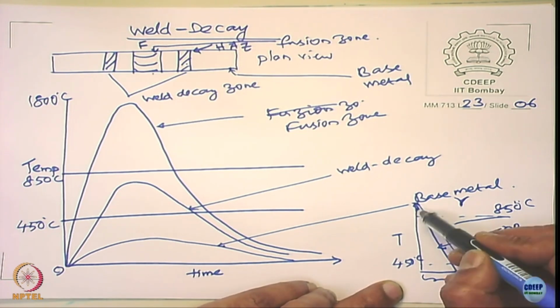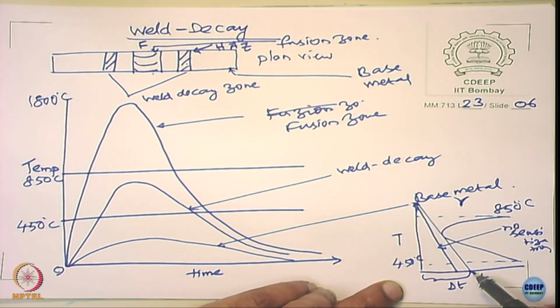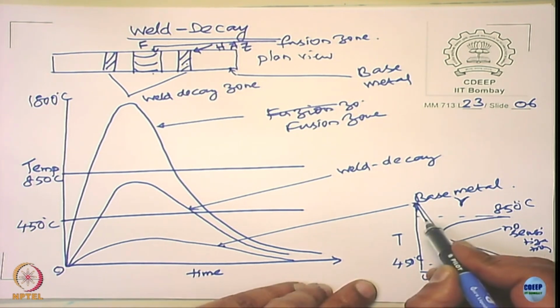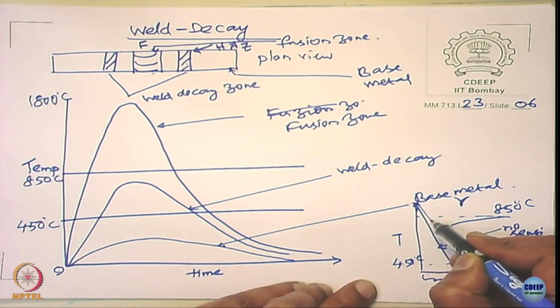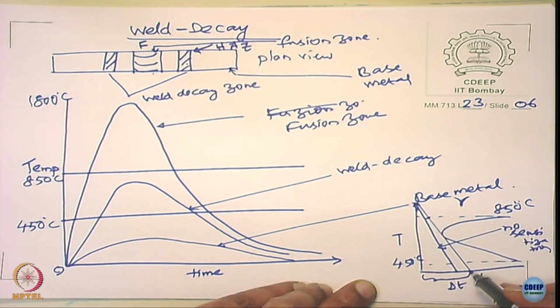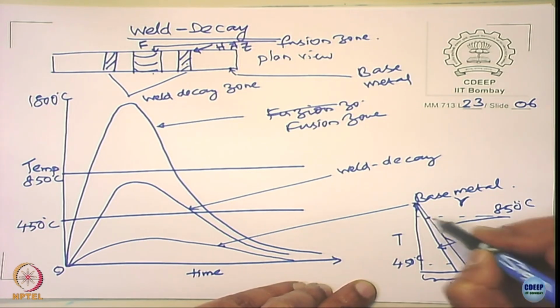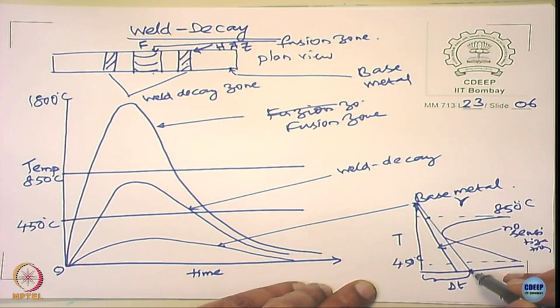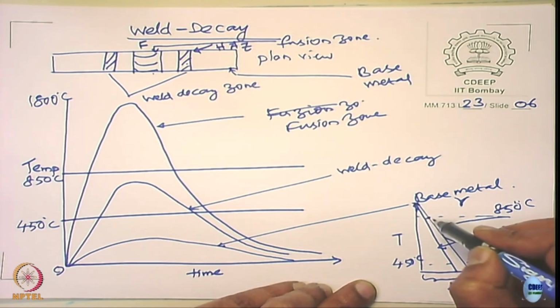So when you take it to this temperature, if you cool it faster than this, that means less time, no problem. Slower than that, you get into sensitization. That means the time that can be held in this temperature region, or actually speaking you should go from here. If you really look at it, this is the time and this is the time, am I right? Time starts from here and goes here.